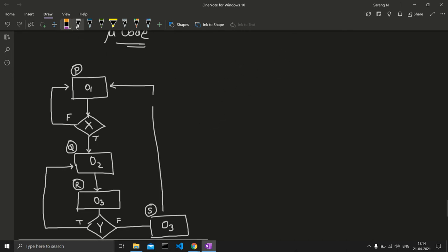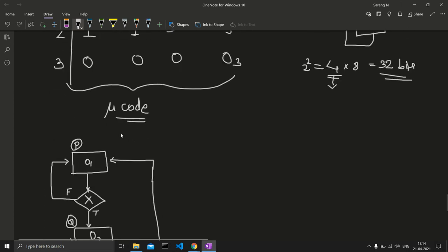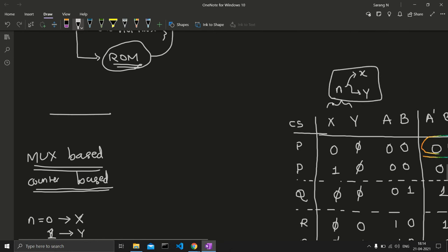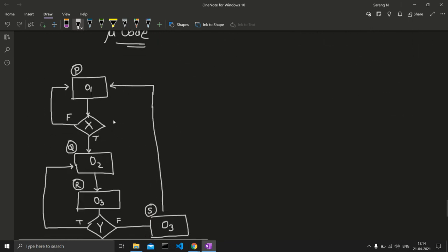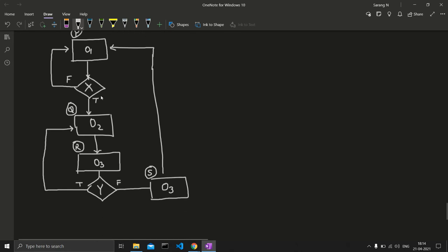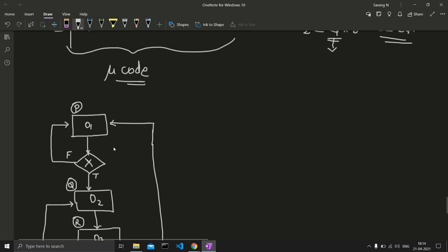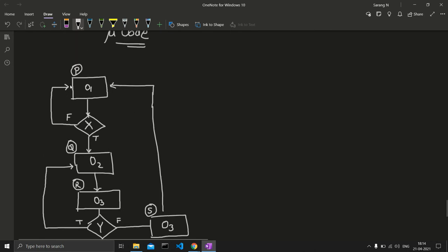You would understand why we are doing this, but just for the sake of it, I'll tell you. On every variable, for microcode we have to do this. Every state should be dependent on only one variable, either x or y. So we already have this in the ASM. If we don't have this, we expand with the technique we discussed earlier.